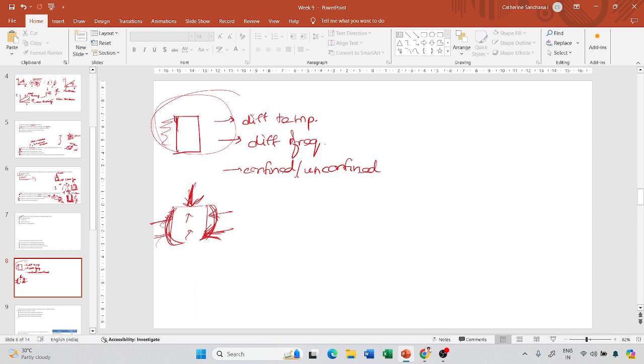So if you see, it has to capture the influence of frequency, right? So when does this frequency occur? My loading has to be periodical. Okay, it cannot be a time domain test. What do I mean by a time domain test? I cannot simply apply a constant compressive force to the sample.